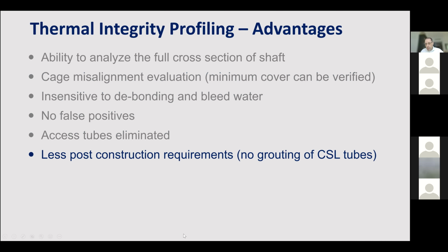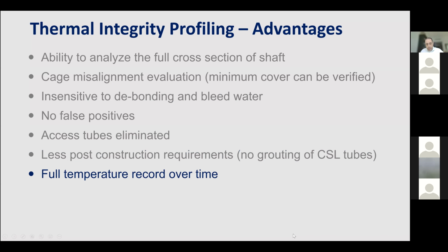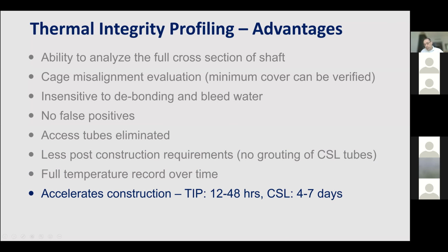There's no post grouting. You can have a full temperature record over time. You can accelerate the construction, so you can have the results within 12 to 48 hours compared to the cross-hole from 4 to 7 days. And of course, the bigger advantage now is the virtual data collection. So travel restrictions, safety requirements, all these things are advantages, as you don't need to go and visit the site to collect the data.